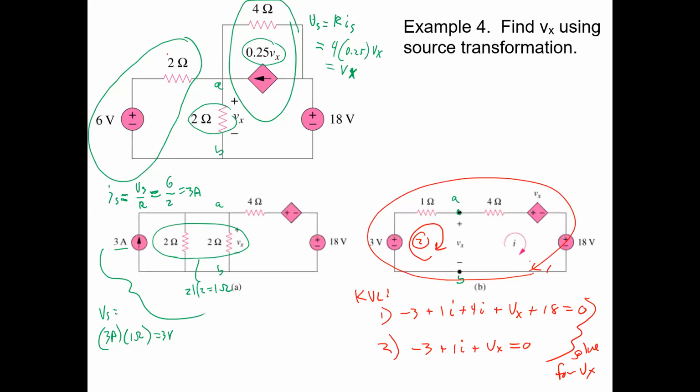Well, you can certainly combine parallel resistors anytime, like we did right here. That's totally fine. But your question was, why did that end up here at 1 ohm above there? It did that because we turned that current source into a voltage source. That's a transformation, and that transformation requires you to move the resistor so it's in series with the voltage source. Right, it's a two-step process.